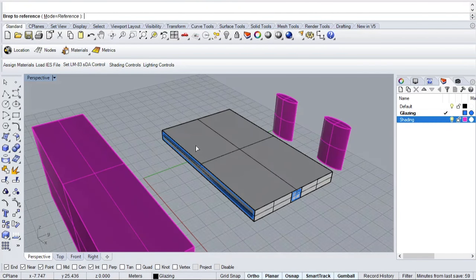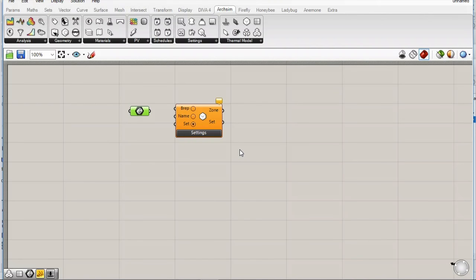And when I do it, it will automatically send me back to the Rhino space. And the intent here is to click on what you think is the body brep that you want to bring into Grasshopper. And in this case, it's the actual gray default building body, building form. Click on that, and right away, it brings you back into Grasshopper.